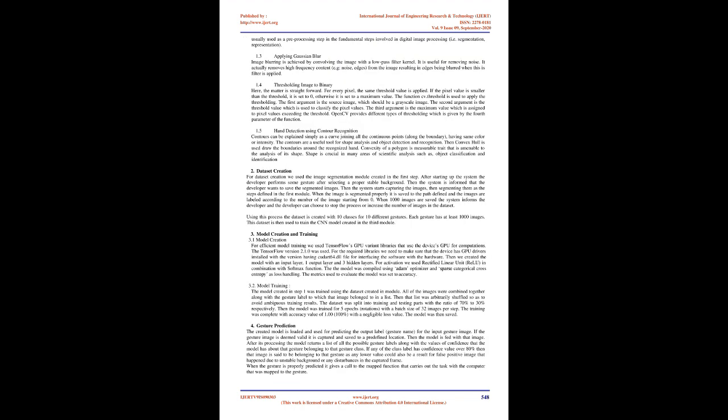In this paper, linear discriminant analysis, LDA, and extreme learning machine, ELM, are implemented in a hand gesture recognition system, which is able to reduce the redundant information in SEMG signals and improve recognition efficiency and accuracy. The characteristic map slope, CMS, is extracted by using the feature re-extraction method because CMS can strengthen the relationship of features cross-time domain and enhance the feasibility of cross-time identification. This study is focusing on optimizing the time differences in SEMG pattern recognition. The experimental results are beneficial to reducing the time differences in gesture recognition based on SEMG.